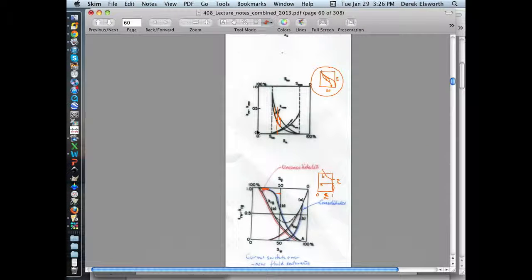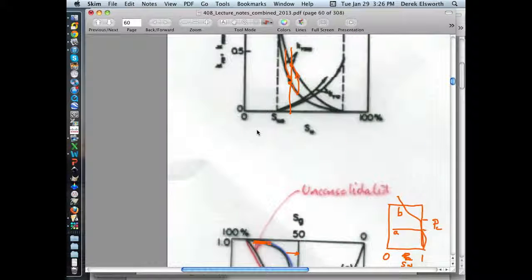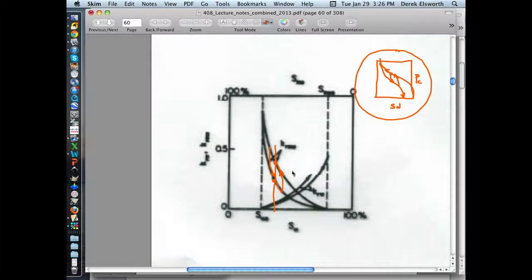And so if we drew our curves actually to replicate the fact that this does this, but this is already bottomed out, then indeed the permeability of our other phase would be, instead of 0.7 and 0.05, this one would be nothing, and so there'd be no flow in this particular case.